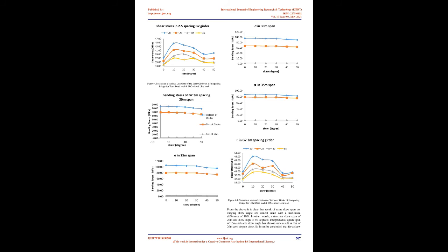Four loading cases are considered for each prototype bridge: central and eccentric live load, bridge dead load, and superimposed dead load (SIDL). It is clear that the trucks are moved in the transverse direction within the lanes in order to yield the maximum moment in both the exterior and the interior girders. The trucks are also moved in the longitudinal direction in order to yield the maximum moments.